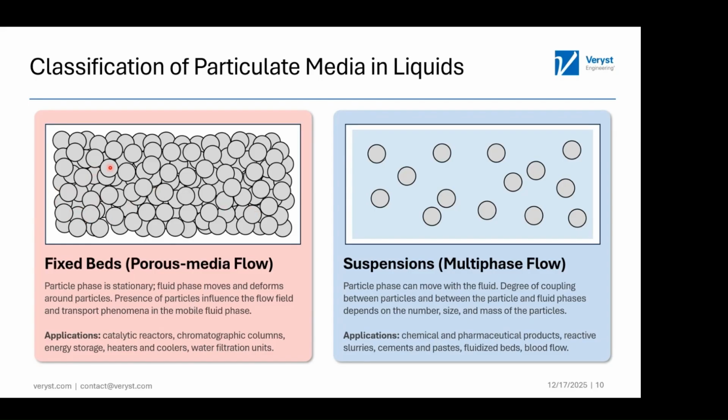The flow does interact with the particles, but you don't have to resolve the particle motion, and so you have fewer degrees of freedom to solve for. And this can be solved, as I'll discuss, at any scale, from the micro to the macro scale, and it's involved in a number of applications: reactors, chromatography columns, absorbers, heaters, and others.